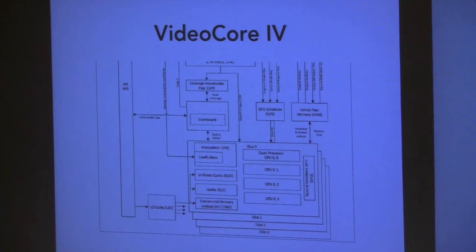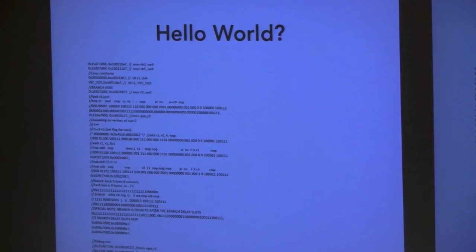What we were really targeting is this, well, each one of these is a QPU. That's effectively what runs the shaders. Each one is a SIMD processor. It lets you do 4 32-bit operations on 32-bit floats or ints. And it can actually pipeline that over 4 cycles, so you can get 16 in 4 cycles on each one. You have 4 of these sharing some cache, and you have 3 slices. The documentation basically says that you can use 4, but we found you can use 3.